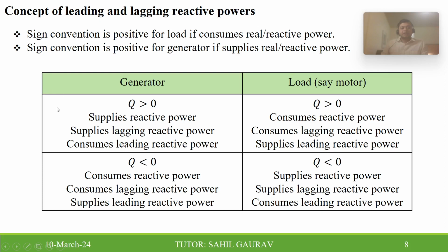No, it is not different. You have to clarify what type of reactive power it is. Like for a capacitor, Q is coming as negative, so that means it supplies lagging reactive power. And if you have an inductor, Q is positive, so it consumes lagging reactive power.